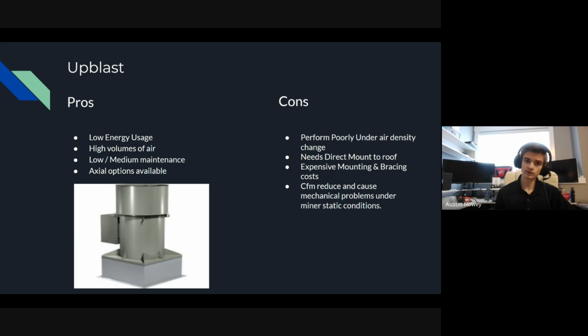And there are a lot of different environmental aspects too that we're going to get into, like where gravity can actually push the hot air closer to your elevation, and it can create that problem where you're cycling your own heat from the little bubble of hot air atmosphere that you're creating around you, and you're just cycling it back down into your intake system.